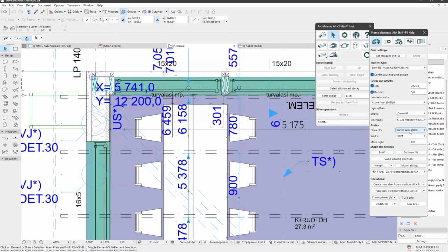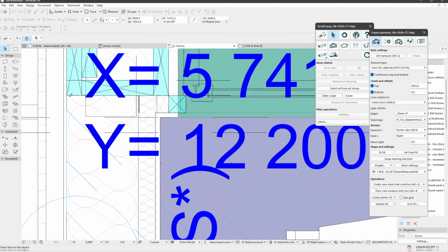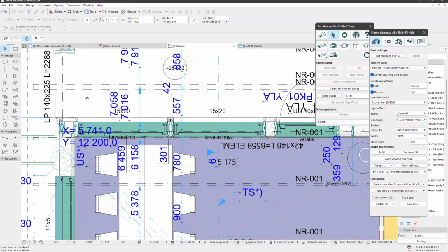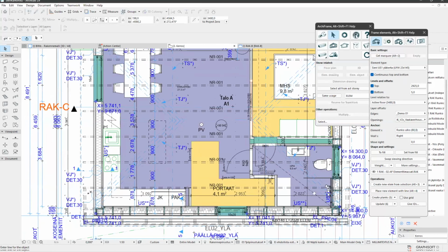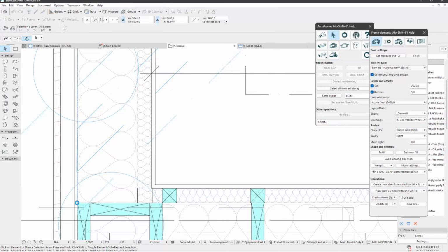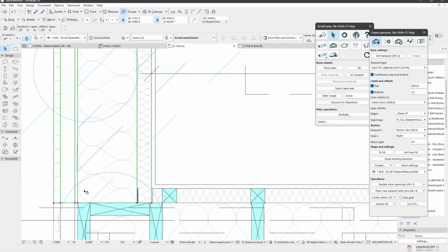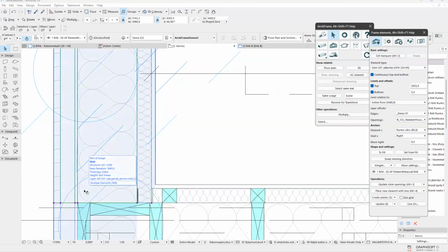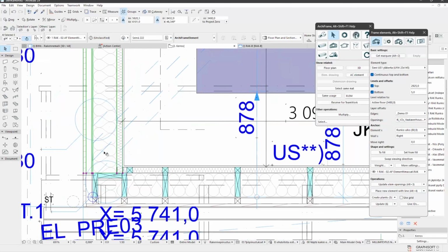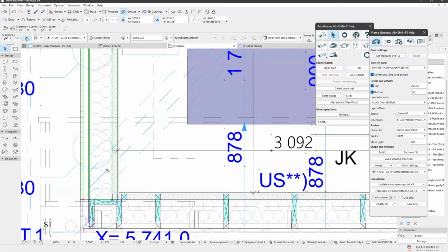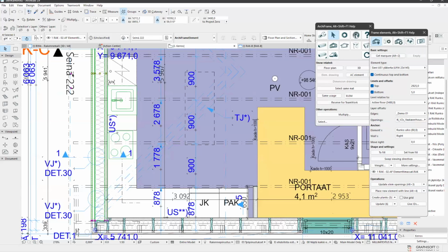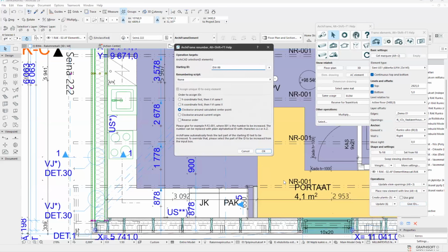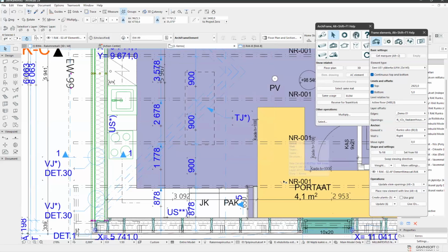And now I'm going to show the place for my element by line, showing the exterior side of the load-bearing core. So I draw over the architect model, and if this was a very long wall, I could split this into 2 or more parts to have multiple prefabricated elements, but this is short enough to be lifted as a single element, so that's fine. And our element got its ID from the architect wall, and I see the architect hasn't really given an ID, so now it is time to have a unique ID for each of our elements.